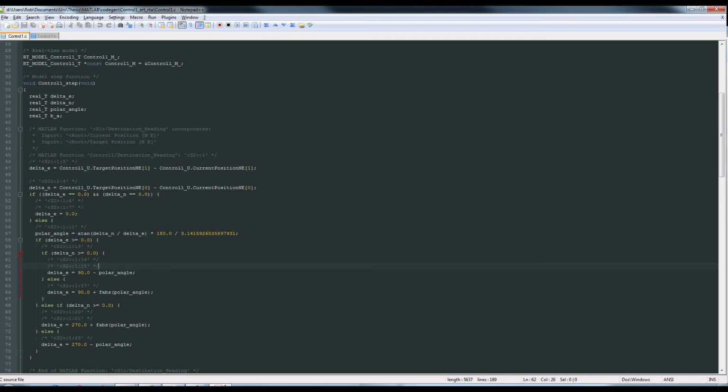Finally, the code generation toolbox built into Simulink allows the control algorithms to be easily integrated into an embedded system using generated C++ code. The same inputs may be used based on real-world sensors to produce an output that controls the thrust of the motor along with the direction of the motor. This allows what are relatively complex systems to be integrated extremely easily, reducing development time markedly.